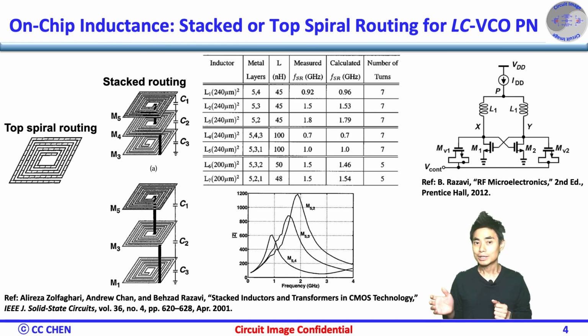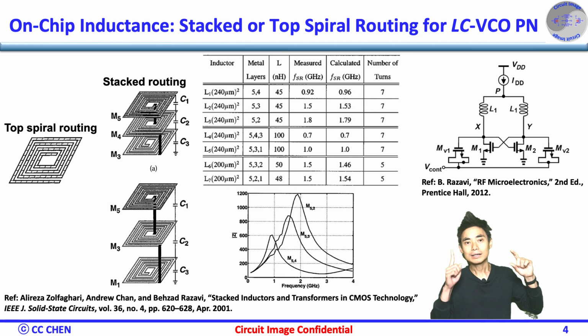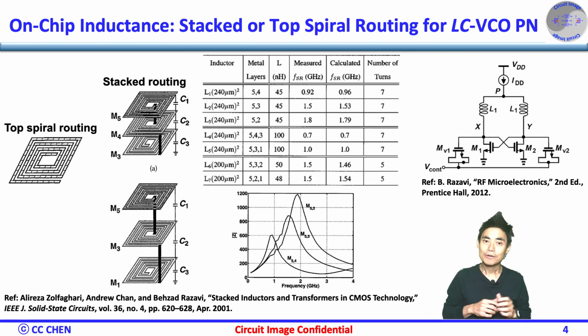Even looking at the same 28nm process, you may still choose a different metal stack and get totally different inductor characteristics. For example, a higher metal stack with a thick top metal would have a higher quality factor and less resistive loss for the inductor, which may improve the phase noise of any RLC PLL for the serial clocking.